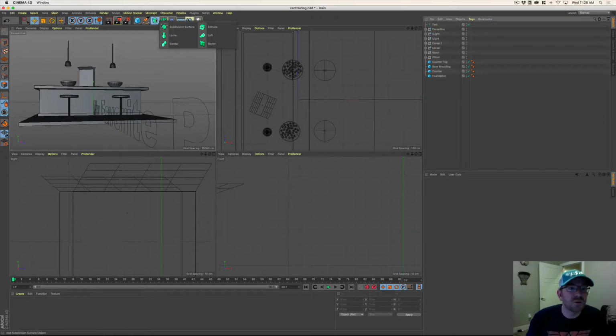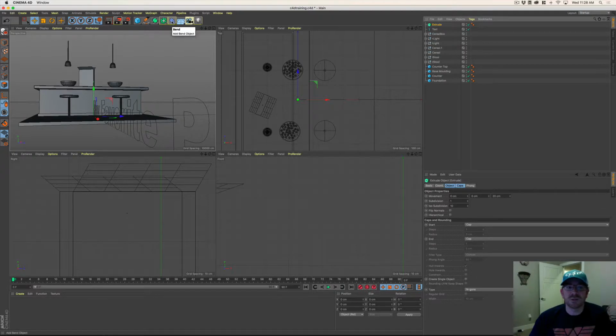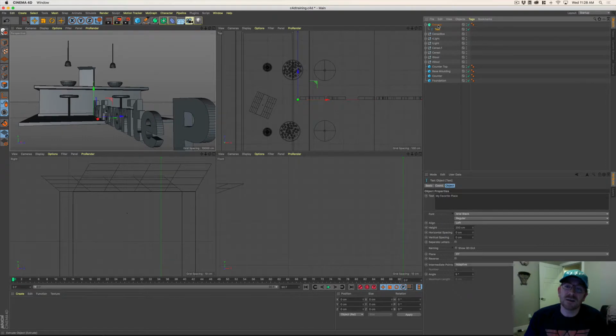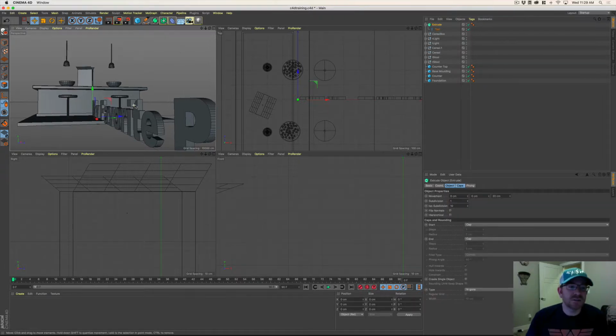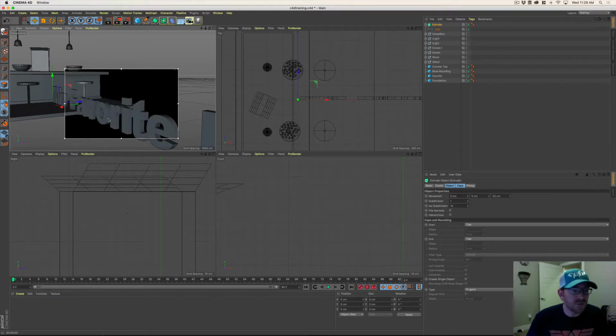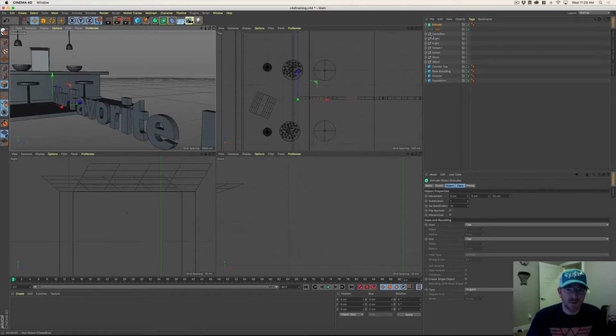So you go to your subdivision surfaces, this little green box with a bounding box, and inside of there, there's an extrude object. This is a modifier, so this modifies things. There's two modifier areas here. There's this area, and there's also this one here, which I probably won't go into, but it's pretty fun. The way you modify an object is you click and drag that object into the modifier, like that. This menu works differently. It works the opposite way, but if you're interested in those, let me know. So right now, it's actually making geometry of your text. It's actually there now because you've extruded it.